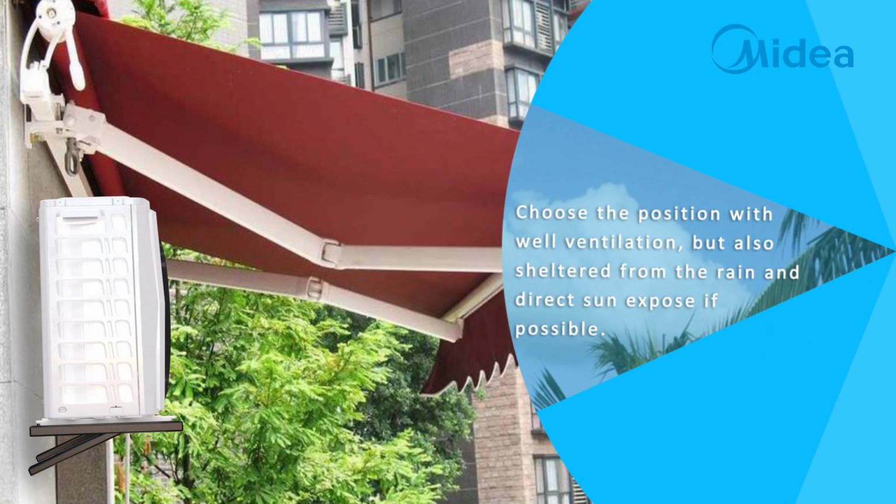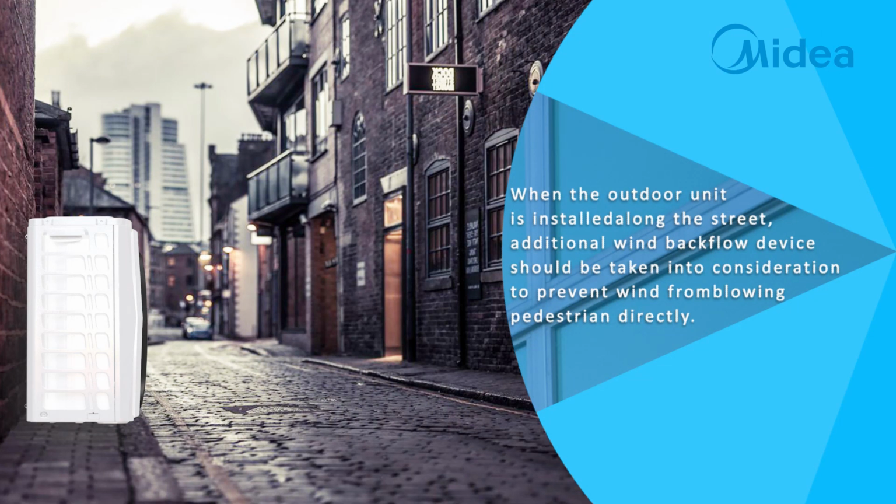Choose the position with good ventilation, but also sheltered from the rain and direct sun, if possible. When the outdoor unit is installed along the street, an additional wind backflow device should be taken into consideration to prevent wind from blowing on pedestrians directly.